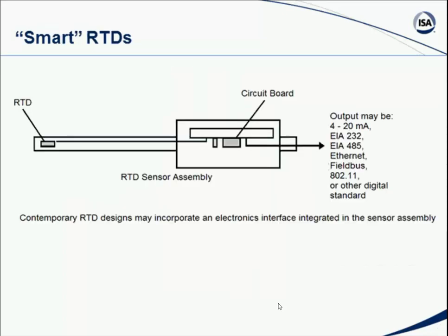Now, as I mentioned, RTDs, especially if they're placed a long distance from where the measurement instrumentation is located, have this problem of correcting for their lead error. Today, in fact, it's much more common when you buy an RTD for an industrial application that it comes built in together with both the metal probe to support it and also the head that usually mounts onto the side of the tank or wherever you're inserting the RTD into, with a conduit fitting. There's circuitry inside there, right there, generally, to convert the RTD to some other signal.